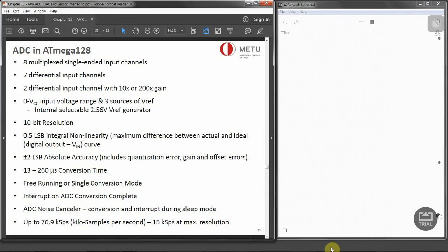So the only thing that we need to be careful over here, as it offers us 16 bits, but our ADC is 10-bit, we have 6 unused bits on the registers. So we can configure this ADCH and ADCL to be either left justified or right justified, which we are going to see in the following section.